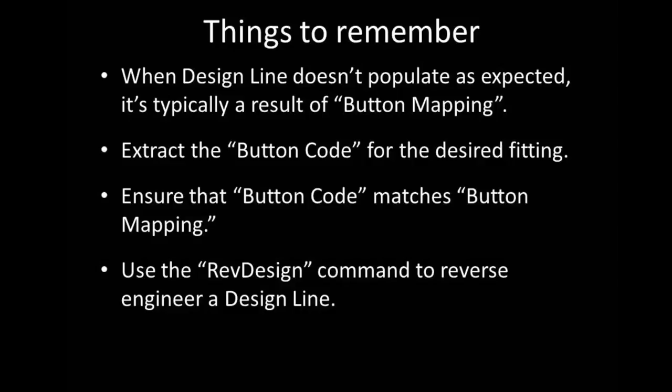And finally, use the rev design command to reverse engineer a design line, and that will let you know if you're on the right track or not, right? So as you saw, I had drawn the same design line, and when I reversed engineered it from the reducing T, it was the exact same thing. So the rev design command can come in pretty useful for troubleshooting.